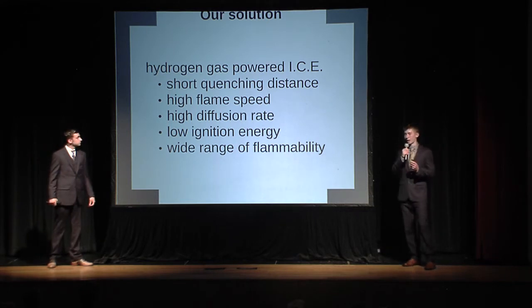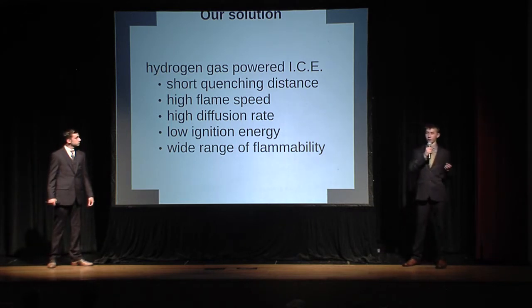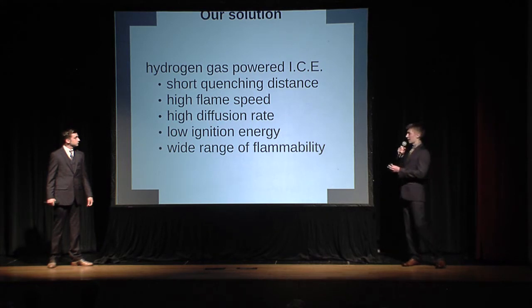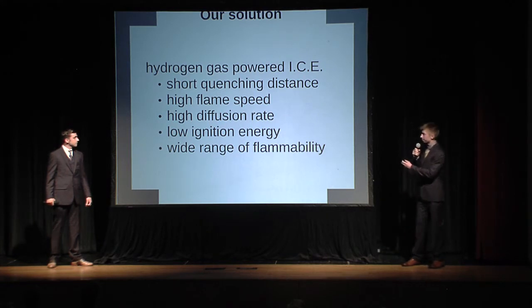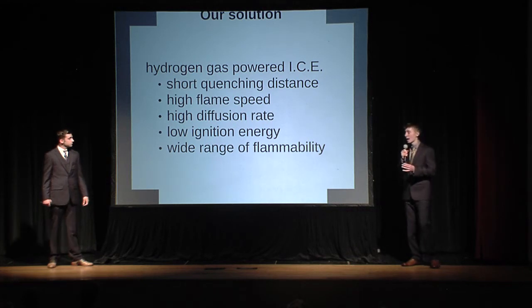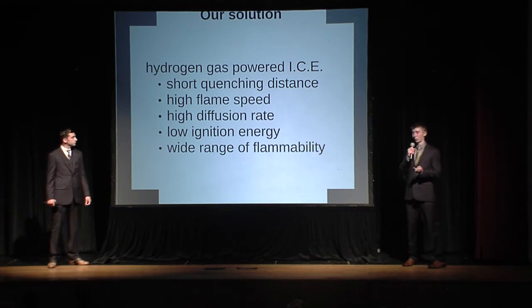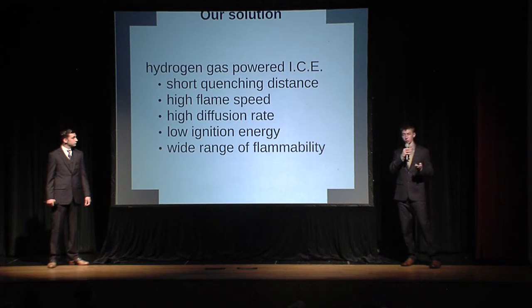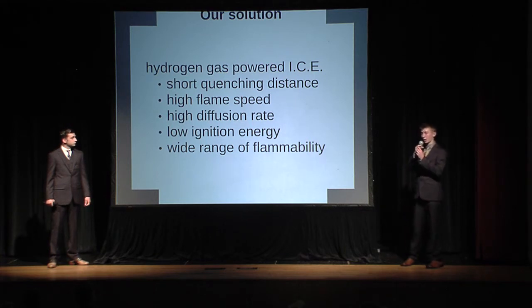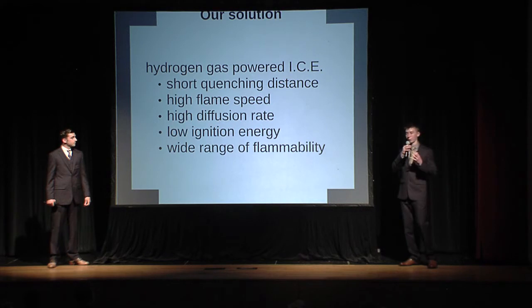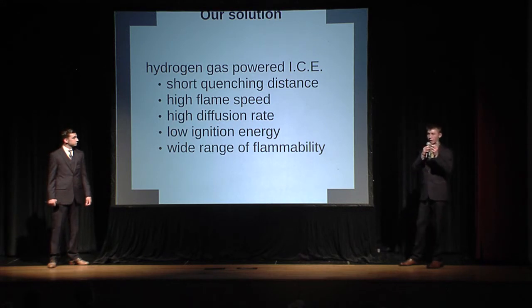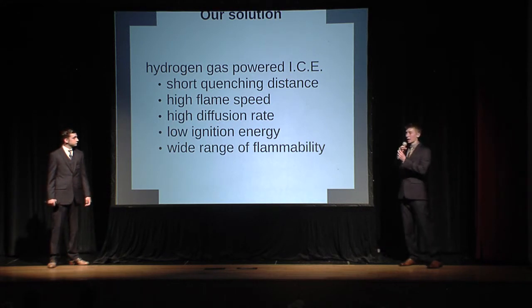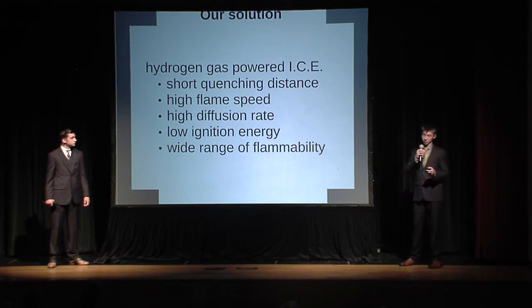Hydrogen has multiple properties that far exceed the performance of gasoline. It has a very short quenching distance, high flame speed, high diffusion rate, and low ignition energy. What all this means is that it can produce a better, more homogeneous mixture in the combustion chamber and explode and detonate more completely and efficiently, getting all of that potential energy stored in hydrogen and using it to actually turn the pistons in your engine.